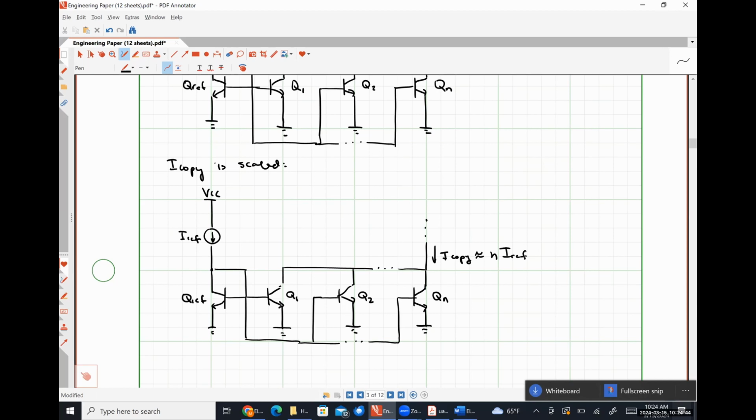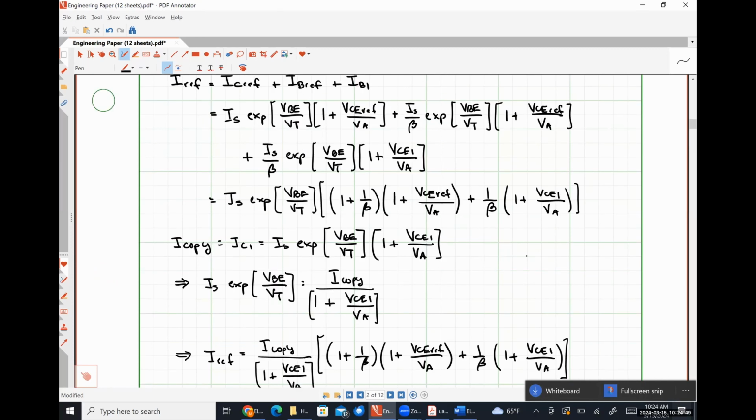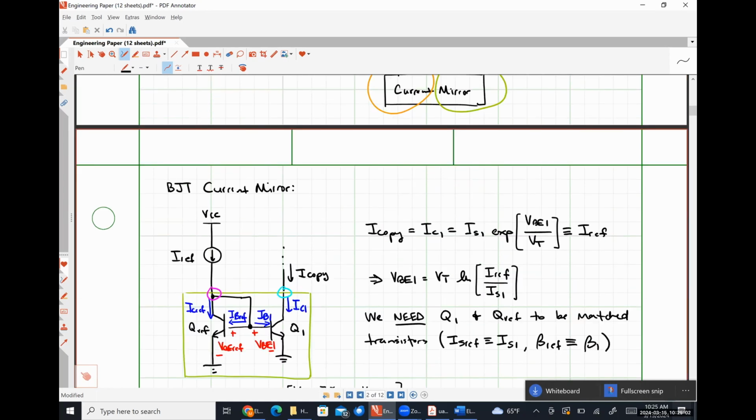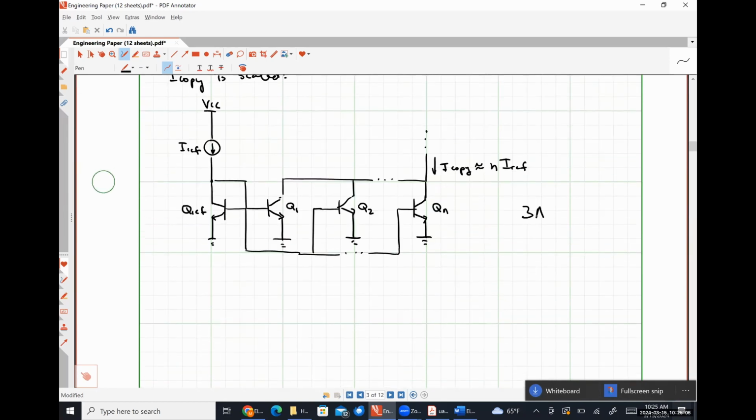Okay. Now, I'm not going to draw it like this probably ever again. Instead, I'm going to do something like we saw right here. I just put N telling us the number that we have in parallel. So typically speaking, we might represent 3 transistors in parallel as something like 3 AE. We represent it by 3 or whatever number AE because effectively what we're doing is scaling up the area of the emitter when we put those things in parallel, which is realistically how the device functions. So 3 transistors in parallel is the exact same thing as a single transistor that has triple the emitter area. So that's how we represent that.